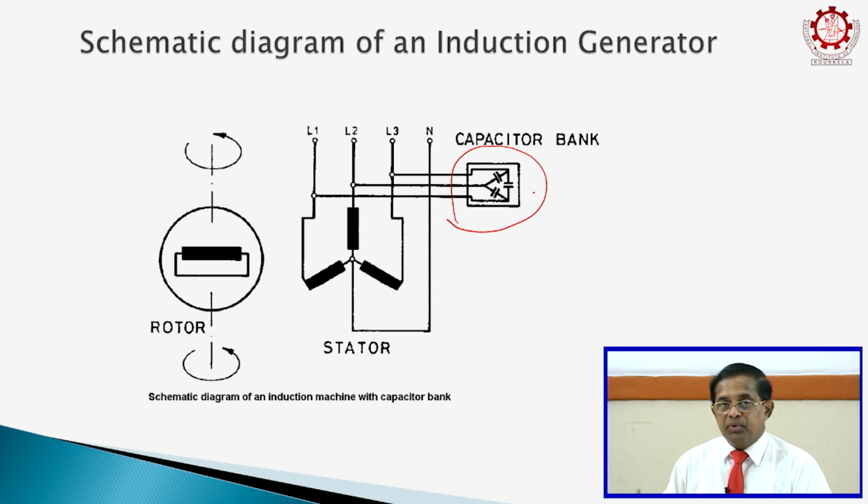Now, we want to put up a power plant and sell electricity to the grid, right. Now, the grid operator will have numerous problems. One issue is whether at all he has a transmission line or grid substation close by, and also if the grid substation has additional capacity. Already there may be several power plants connected to it, maybe wind, maybe solar, maybe hydropower, because these power plants are connected on the load side, the distribution side. They are coexisting with the loads and consumers.